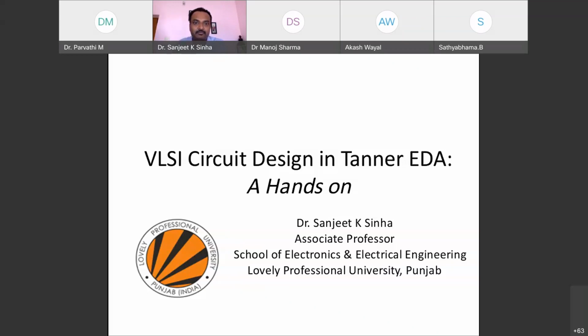Okay, sir. Can I use Verilog for that, or specifically Sentaurus TCAD only am I supposed to use? No. Here there is no use of Verilog. You can go for TCAD, that is Synopsys TCAD or Visual TCAD. In that, you have to design a MOSFET, a single MOSFET, P-type and N-type, by using FinFET technology.